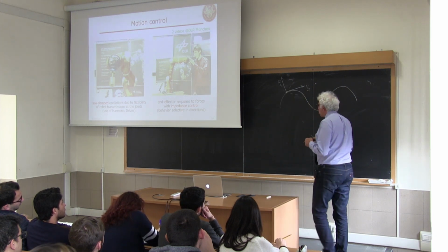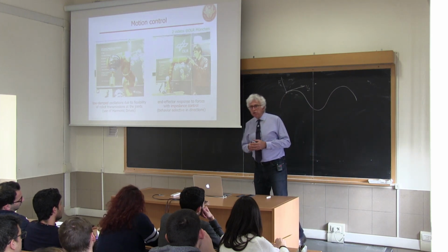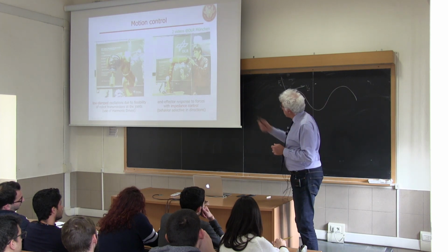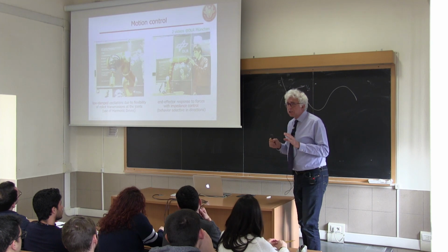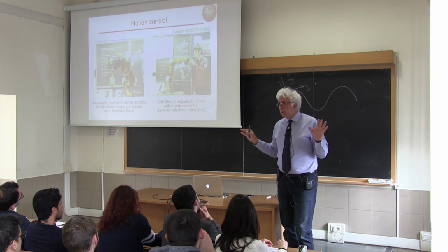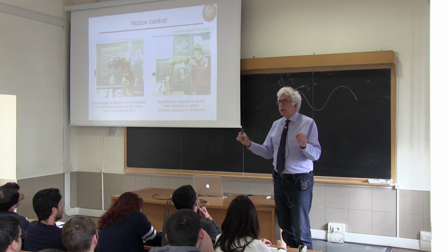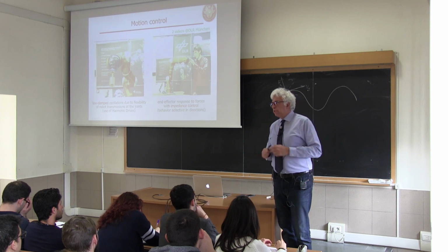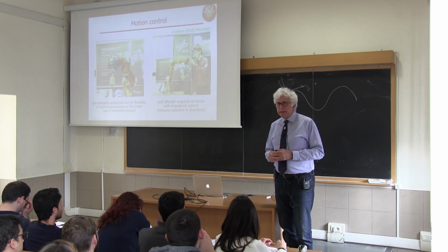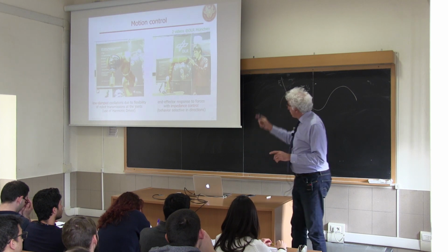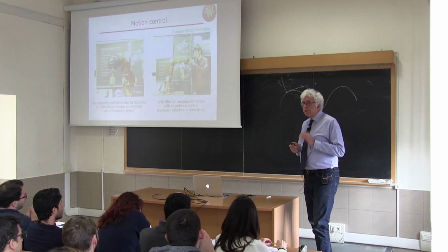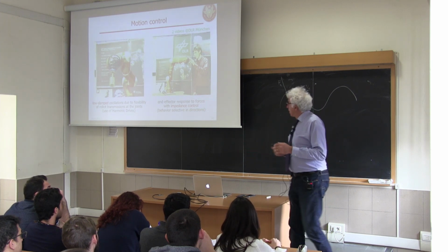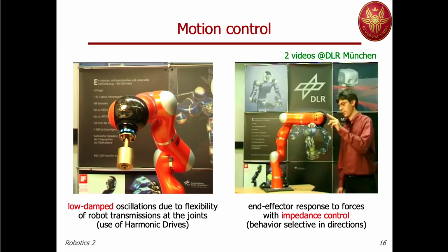Now, compliance on one joint, on the second joint, on the third, up to the seventh joint, if you sum all of them together, you will have a situation like the one on the left, where the robot is commanded to stay in position. So, the current position is the target. The motors are braked in that position, or you can use high positional gain so that you don't move from there. Still, especially if you add a payload and you give a perturbation, if the system was completely stiff, it would not move. On the other hand, you see this type of vibration.